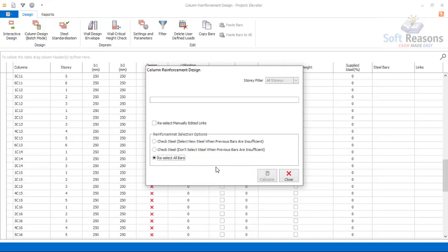So you give the program just some seconds, it is going to calculate and then be able to provide rebars for all of these columns. If there's any section that is insufficient, it will actually identify it as a failed section, which can later be edited successfully. So let's just give the program a few seconds to carry out the design successfully. So it's going to design up to 114 members, you can see here, for all the stories successfully. So design is okay, design is done.